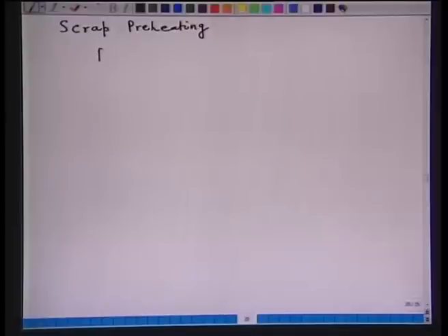Now, imagine, suppose I take preheat temperature here and energy introduced by preheating here, in kilowatt hour per ton. Now, very simply I can calculate it, that is the energy is m Cp into delta T.